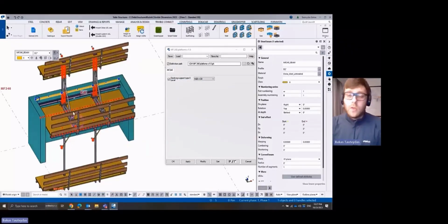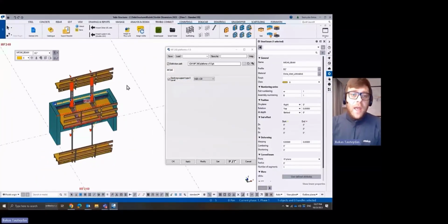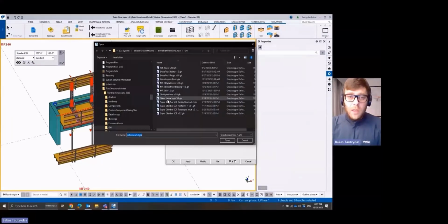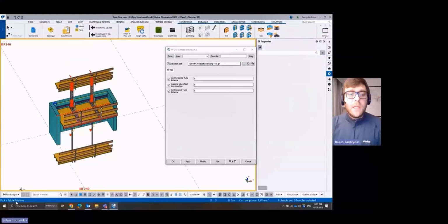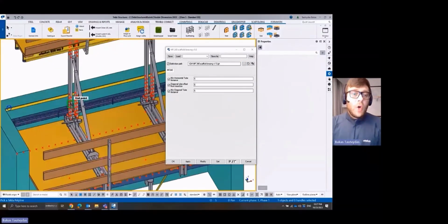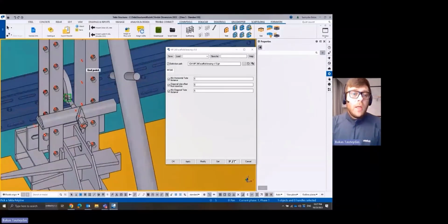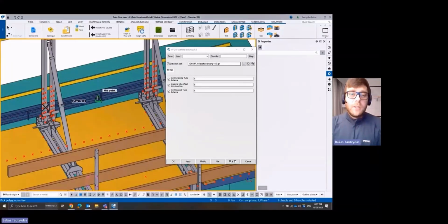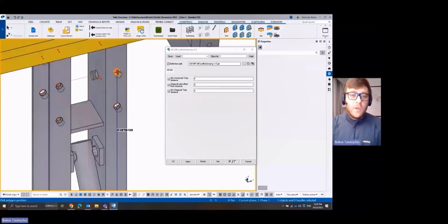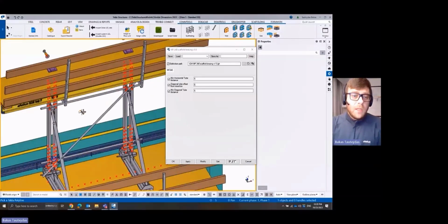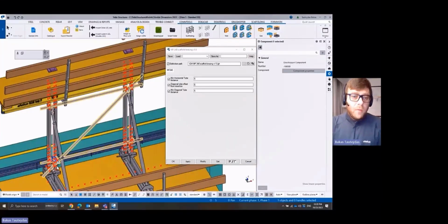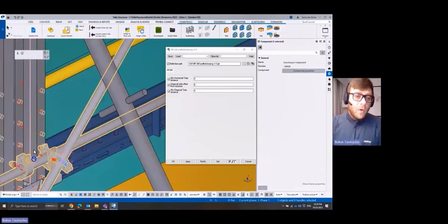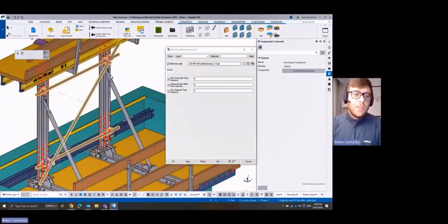And the last example I have here is scaffolding bracing. Let's wait a few seconds, trigger one more time, and you will see this time it is a Tekla polyline. So let's choose one point. Let's choose another one. And also let's go somewhere up. Let's say somewhere here. I'm happy with that. Middle mouse button. In a few seconds, you also get this scaffolding bracing with all the right position and adjustment, which manually would not be so easy to do.